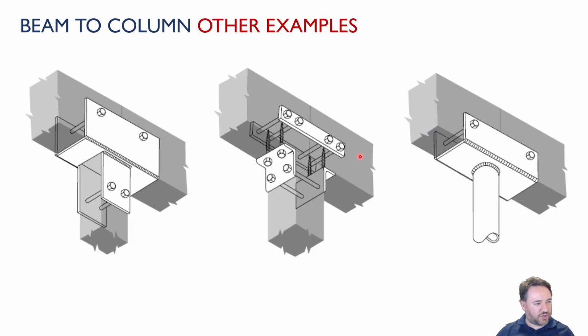Okay, these are just a few other examples of how to connect beams to the top of columns using steel collars. These are all acceptable situations. Again, typically we want these bolts to be about as low as is reasonable when I'm talking about perpendicular to grain shrinkage, because I don't want this to shrink up and then crack. But these are just welded plate connection here.